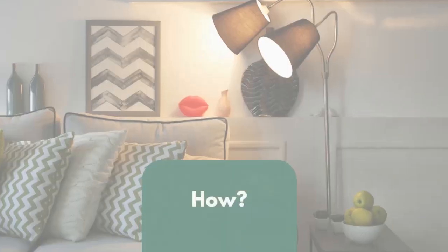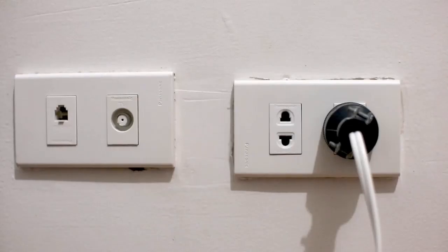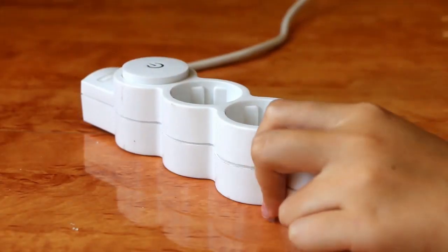How do I incorporate sufficient light and electrical into my design? Step number 1, cater for plug sockets. When it comes to electrical points, always count how many plug points you will need in relation to what equipment you will need in that space. So what equipment needs power, and then cater for that. From here, I then add a contingency of 1 or 2 points as well. So if I need 5 points, I add an extra one just to be safe.